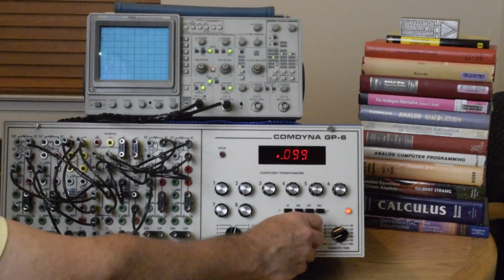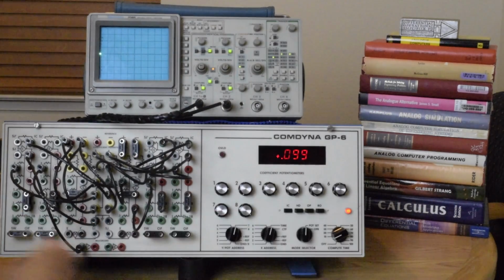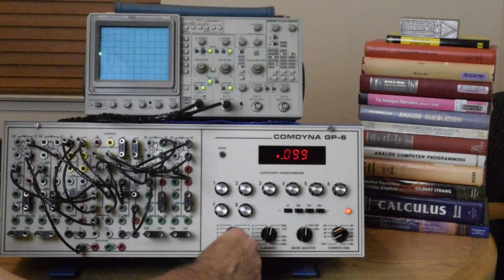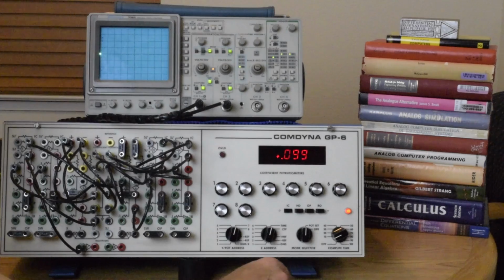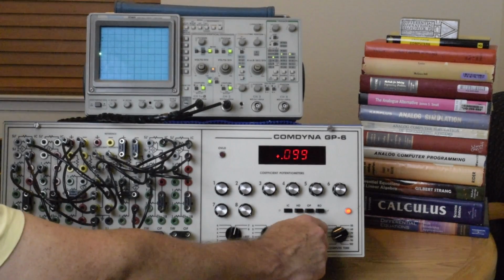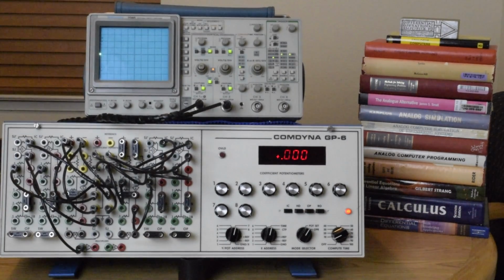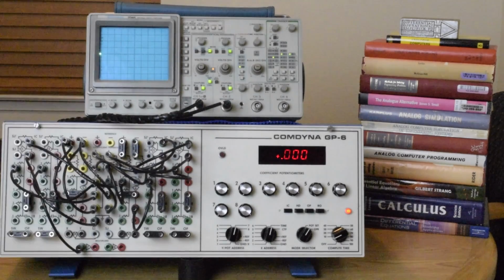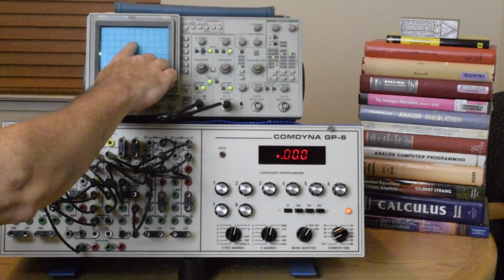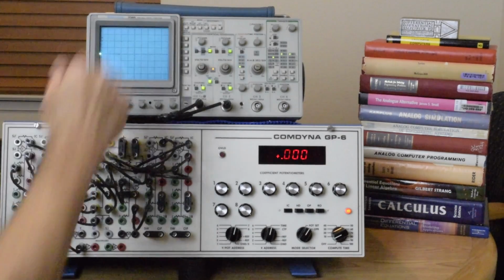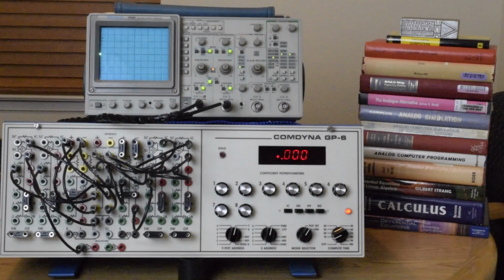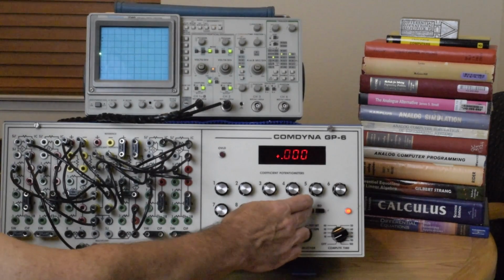Then we switch back to the amplifier that we're interested in looking at the output, which is actually amplifier 7, and switch over to operate mode. Now we're at that initial condition of 0, and with a slope of 1 I would expect it to hit 5 when t equals 5, and then hit 10 at the end of the operation.